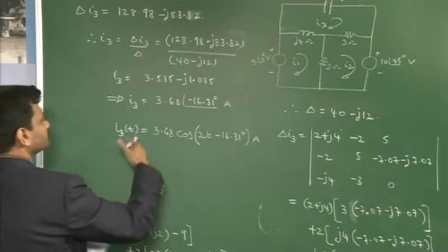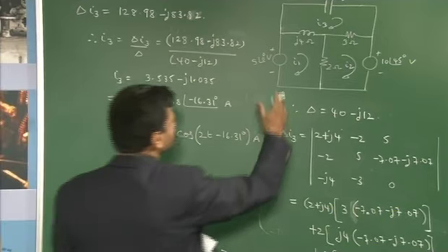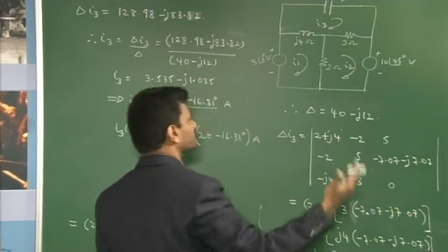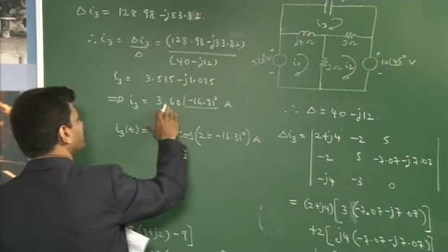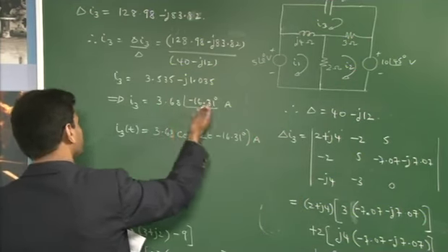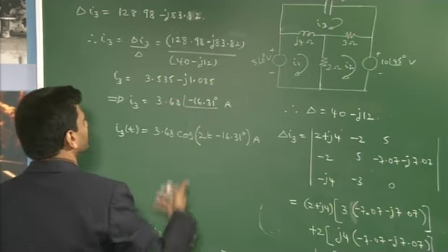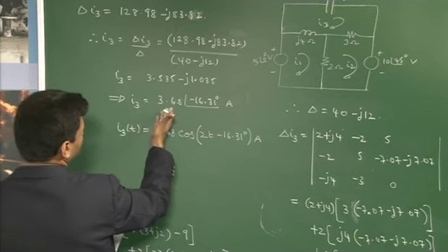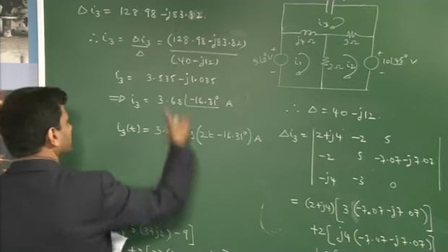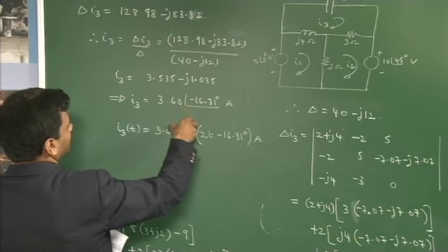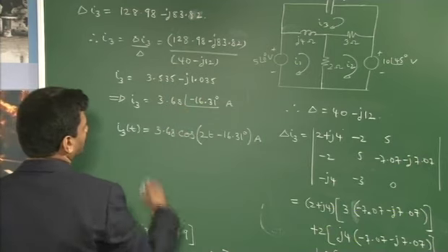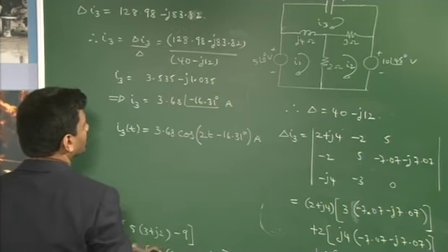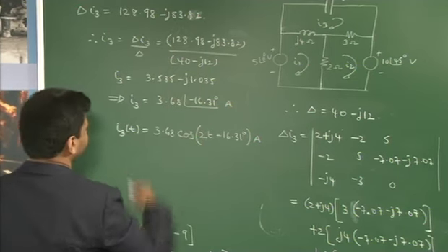So basically what we do, we represent the phasors at our point of reference t equal to 0 and obtain the response phasor, which is again at t equal to 0, and this response gives the information about the amplitude as well as the phase angle. Then this can be used to obtain the steady state expression in the cosine function form in this case.